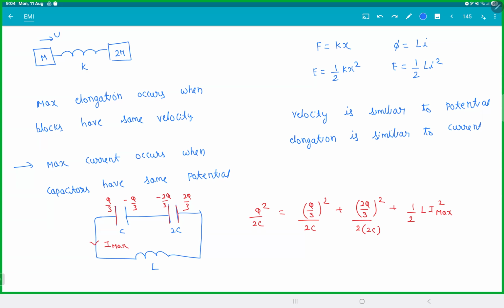You can even keep 2 inductors, 1 capacitor. So if you have an inductor and a capacitor, the capacitor is more than happy. It will take the charge, absorb the charge, give the charge. So it does not fight with the inductor. It will let the inductor do whatever it wants and the capacitor will be there to take the energy. So that's why you have an LC oscillation. In this case, you won't have any dissipation. And you can clearly see how electric field converts to magnetic field and magnetic field converts to electric field. And this is how you make your oscillating circuit.